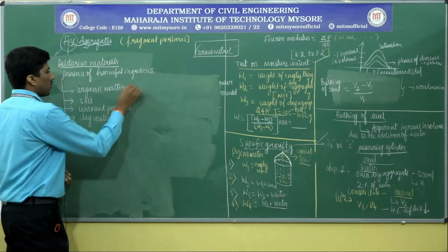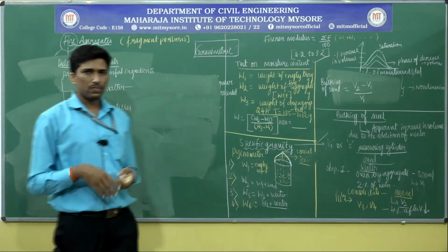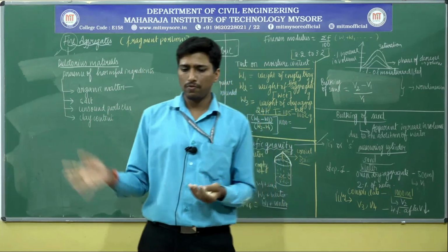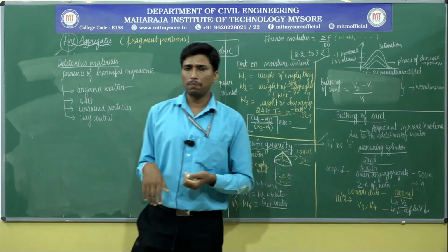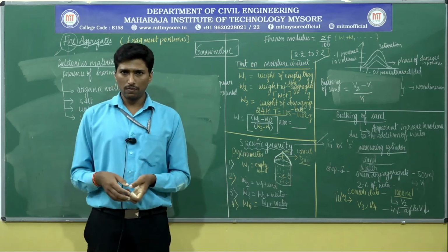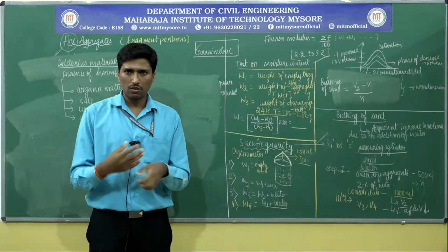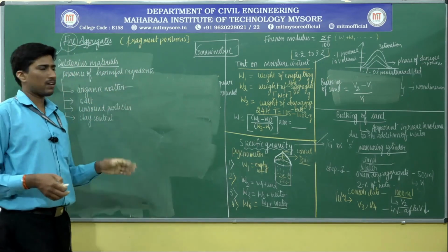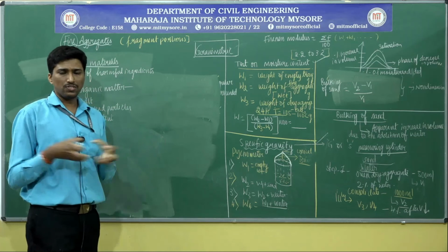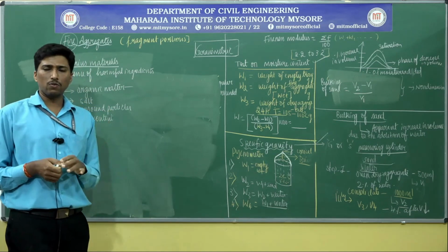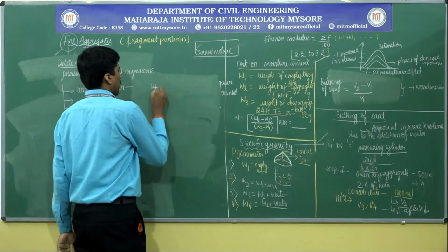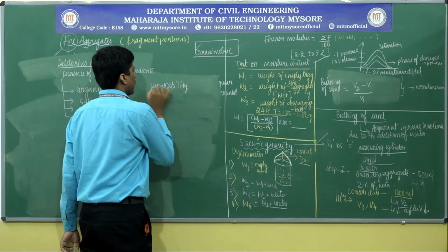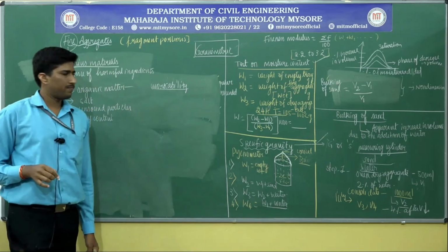Because in the case of organic matter, vegetable or decayed organic matter, the roots are cut apart during extraction or excavation, and they may tend to grow along with this, so it cannot be used for construction purposes. Hence the dead and decayed organic matter tends to even cause segregation, or what I have told, it tends to affect the workability condition.